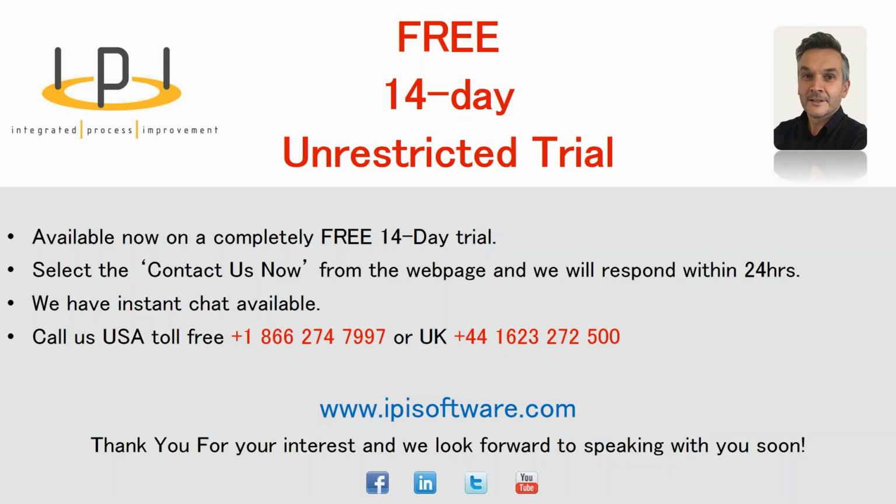The answer is yes. Our data is all on the back of SQL Server, so imagine that as a database. You'll have all your R&R study percentage results against the measurement equipment. And just in particular to that question, what you'll find of interest when you watch the movie is that the tolerance that you use on that particular feature will control the measurement equipment that you see available. So only capable gauges will be listed for you to choose from.